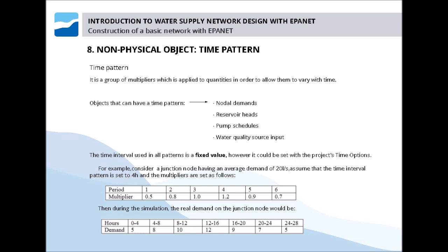Moreover, all time patterns must use the same time interval. Each can have a different number of periods, but all must have the same time interval. When the simulation clock exceeds the number of periods in a pattern, the pattern is reset to the first period.